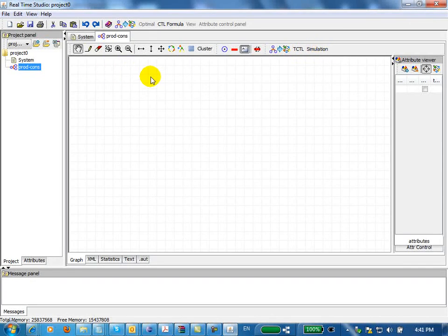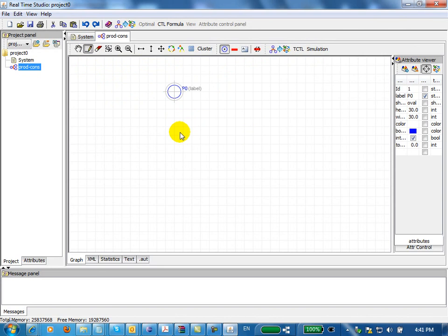So let's start by constructing the Petri net. So I press this button to say that whenever I press a button on the panel here, I get a place. And then I press this button to say that I'm going to be drawing. So when I press a button, I get a place. Now, if you go and click on this place here and you drag, you will start drawing the link, and if you release, what comes after a place is a transition. If you release, you get a transition. If you start from this one and you drag, then you release, you get another place, and so forth. You can draw.